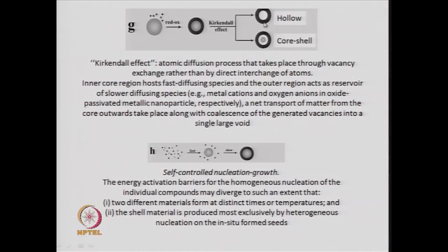So, these vacancies start moving, and the vacancies all coalesce together to form this gap between the core and the shell, and the matter transport is towards the outside. So, net transport of matter from core to the outward direction takes place in this Kirkendall effect.